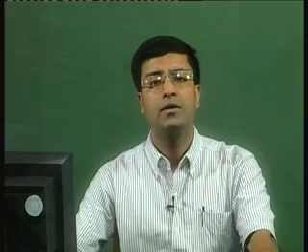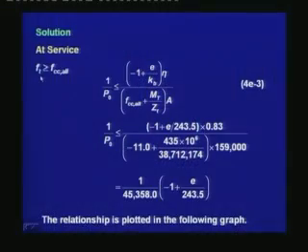Next we are moving on to the stress condition at service. The first condition is that the stress at the top should be greater than fcc allowable. Again this is in an algebraic sense because both these values are compressive. For the corresponding inequality relationship, we have the geometric variables and the total moment.